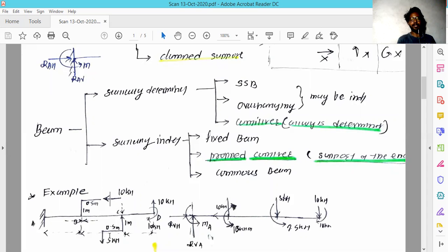And as we know, the force you are applying in the vertical direction also moves to the C point, because it is applied vertically, and the opposite reaction in the vertical link attached to that beam pushes that rod in the downward direction. Just because of that, the 5 kilonewton force is going to act on that point.